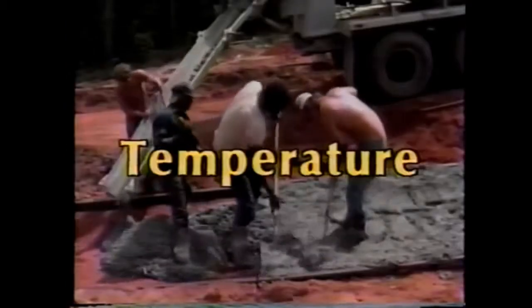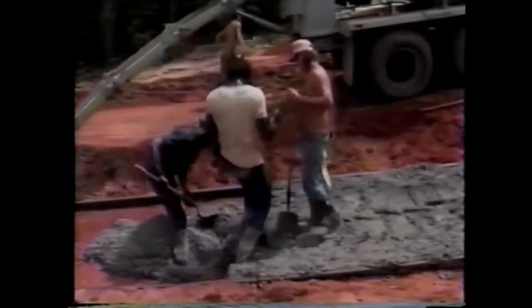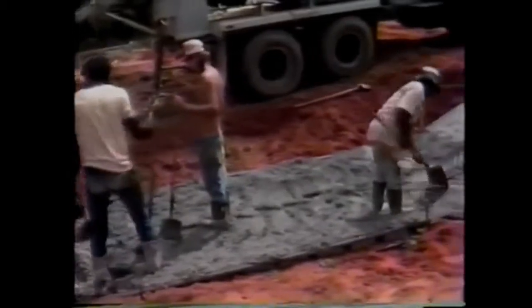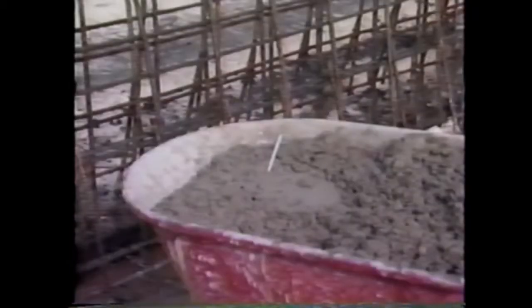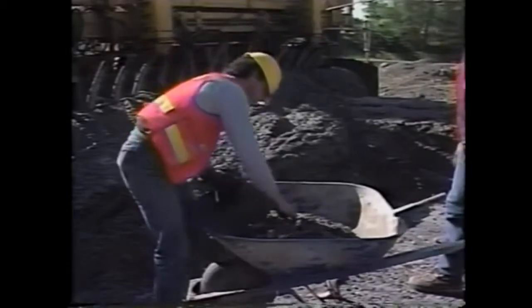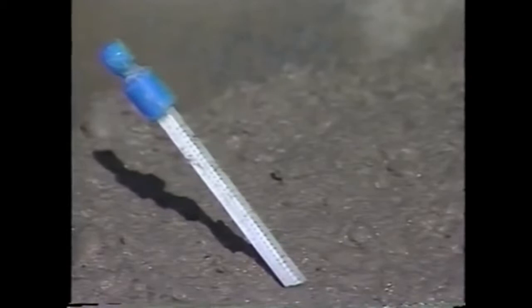Now, temperature. The temperature of fresh concrete affects the rate at which concrete gains strength, the amount of strength the concrete ultimately acquires, and the porosity of the concrete. Checking concrete temperature is simple. The thermometer is inserted into the fresh sample so that the temperature sensing portion is submerged at least 3 inches.